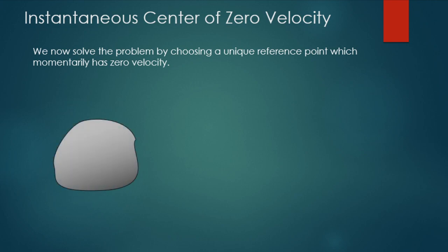So consider this body. So this body is subjected to a velocity at this particular point, and we call it point A. So this velocity at point A, if we locate the instantaneous center by extending the line of action, which is perpendicular or 90 degrees to the magnitude of A, and the distance between this point A and the instantaneous center is what we call r A relative to IC, or r A, the distance between A to IC.